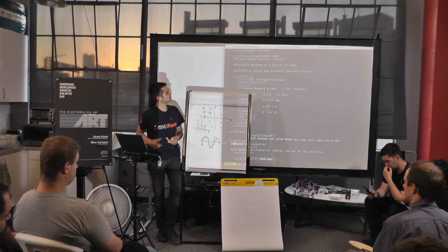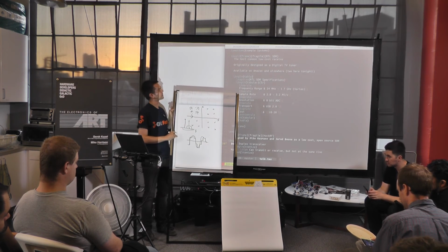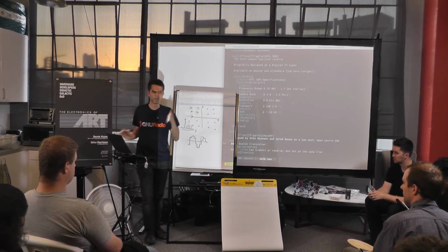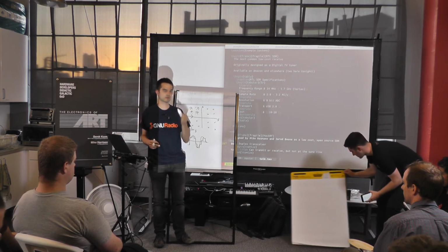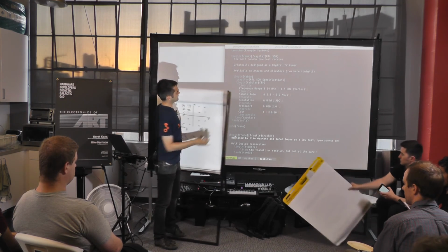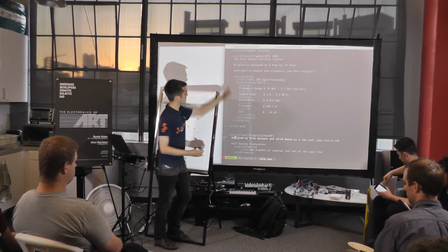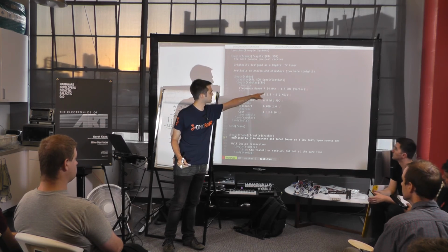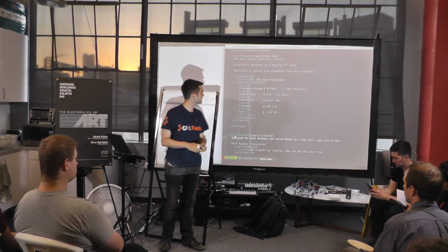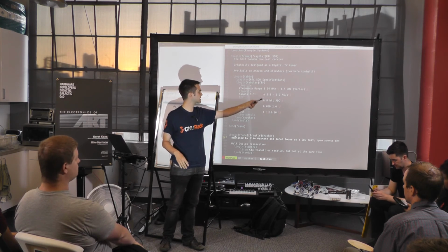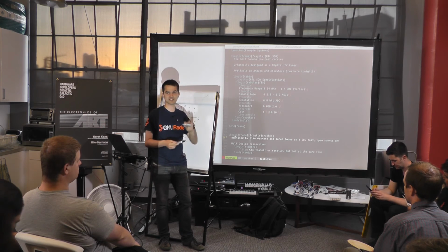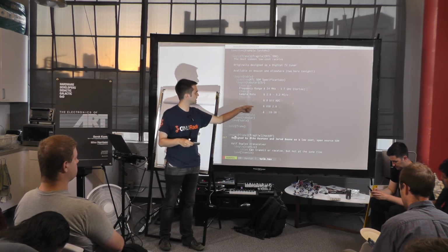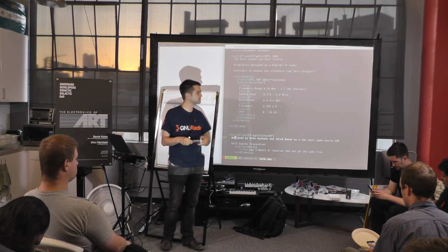Yeah, so some example systems, which I'll wrap up with, because again, my selling point here is that you should go and you should get the $20 one and have fun with it. And then when you finish having fun with this, which won't be anytime soon, you can get one of the other receivers. And so this is an RTL. It goes from 24 megahertz to 1.7 gigahertz. It has a sample rate of, give or take, 2.8 to 3.2 megasamples per second, and that defines how big of a window of spectrum you can view. It has an 8-bit ADC, it works over USB 2, and it's $10 to $20.